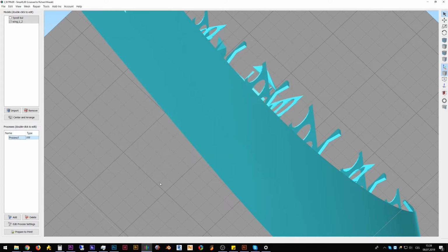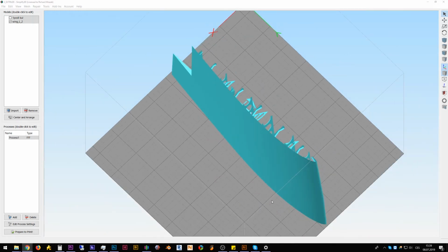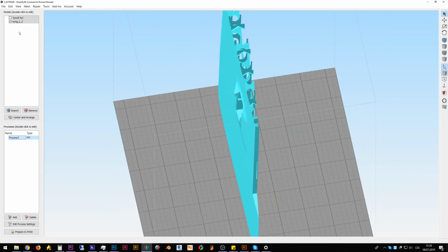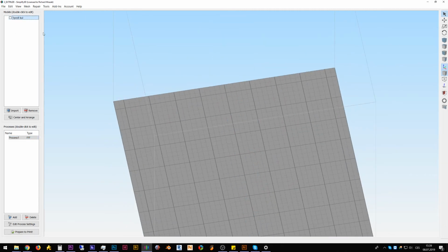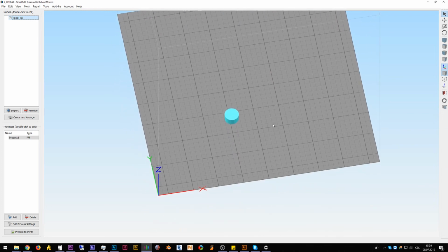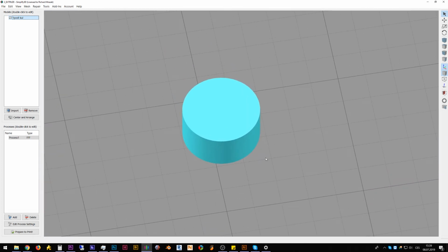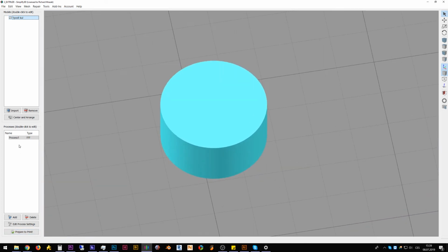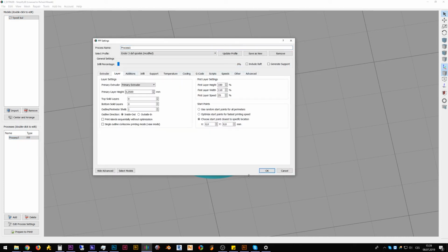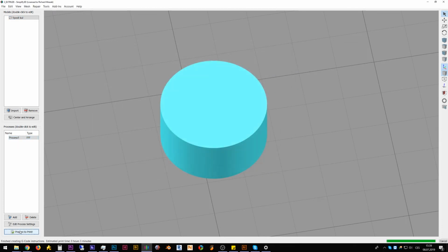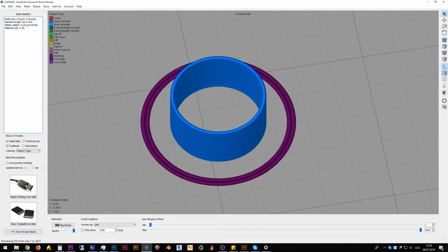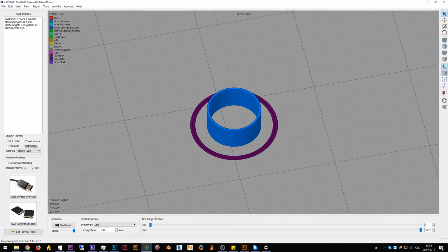I can hide a seam in a print. You know that. I will delete this part and I will show this small circle. You know the seam. Almost on all printed parts you can see a small seam in the place of retractions.